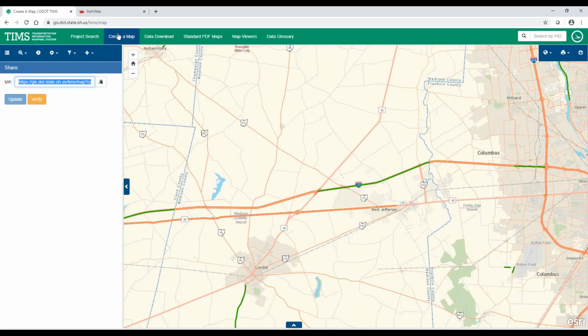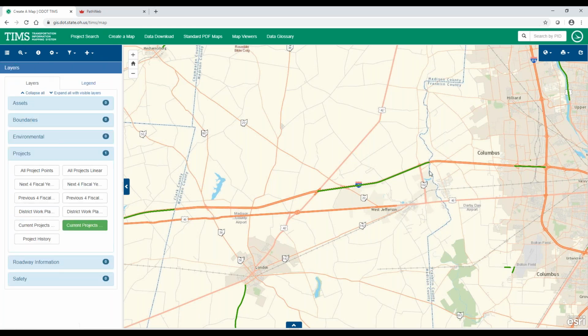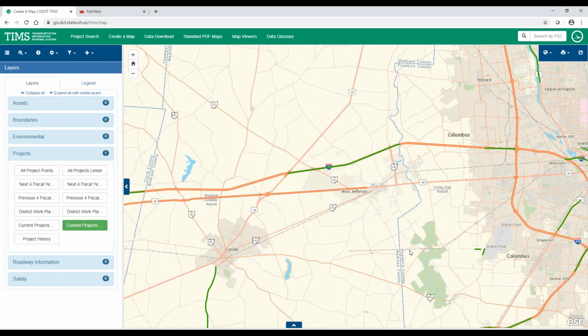Okay, absolutely. Let's get back to our map page. We're in our area and we want to open PathWeb. This little gears icon on the left side pane, we'll call this the layers pane, but it also has this toolbar. The gear is tools. You expand that, choose ODOT PathWeb, and now you'll have your cursor icon. You can click over any major roadway, and we would have driven it.